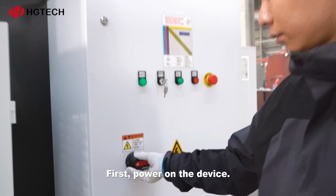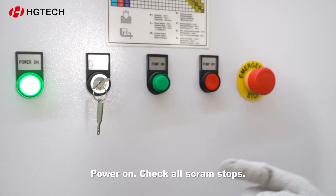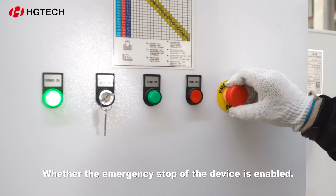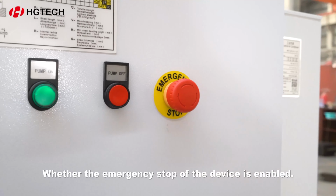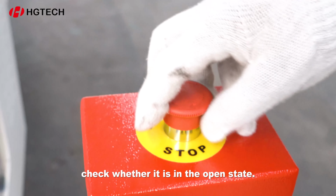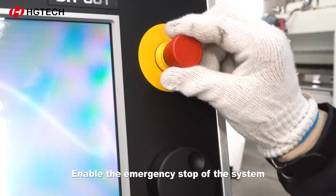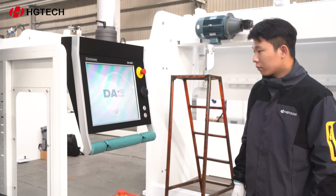First, power on the device. Power on. Check all emergency stops, whether the emergency stop of the device is enabled. Turn on the emergency stop of the foot switch and check whether it is in the open state. Enable the emergency stop of the system and check whether it is enabled.